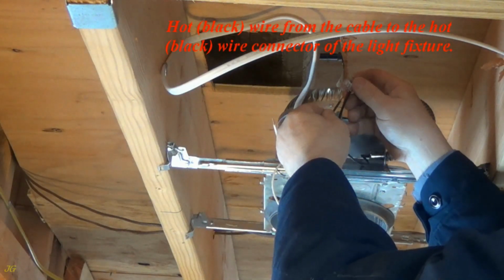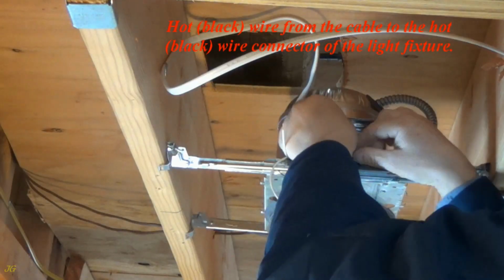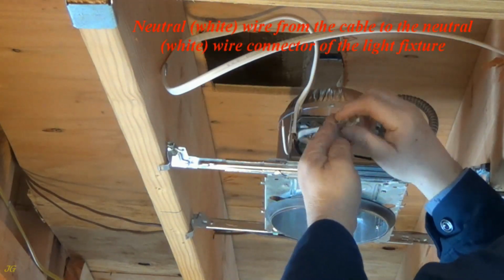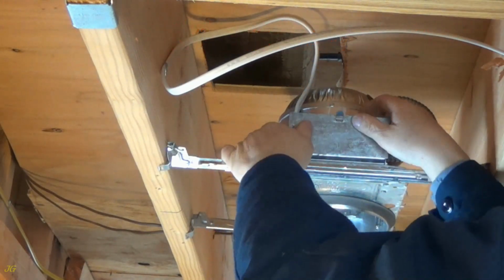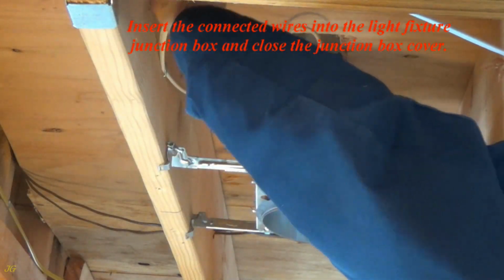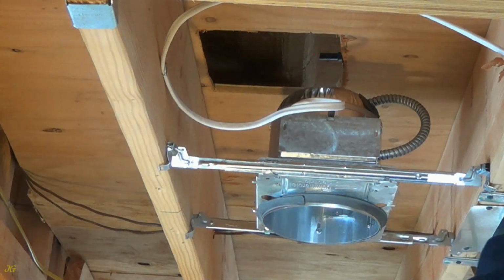Hot, black wire from the cable to the hot, black wire connector of the light fixture. Neutral, white wire from the cable to the neutral, white wire connector of the light fixture. Insert the connected wires into the light fixture junction box and close the junction box cover.